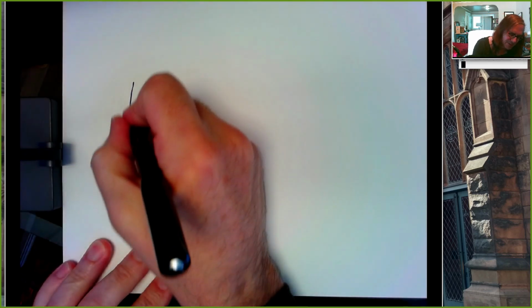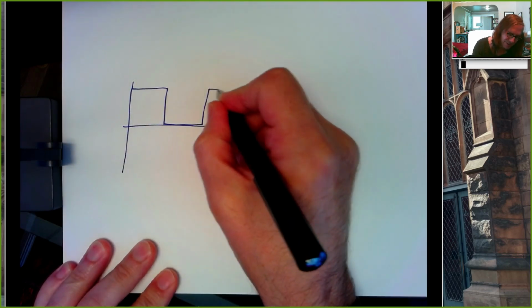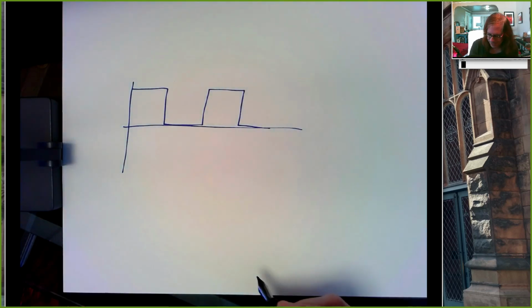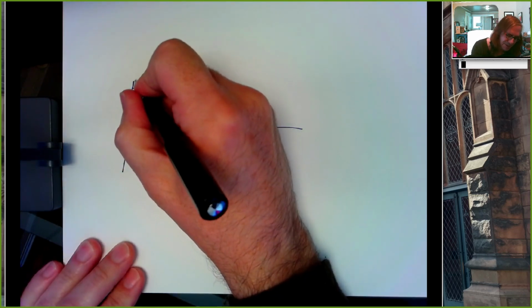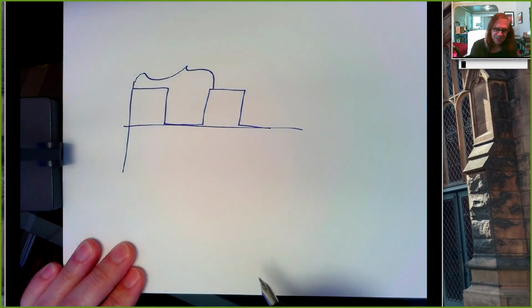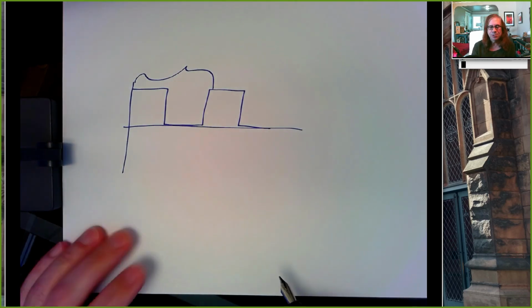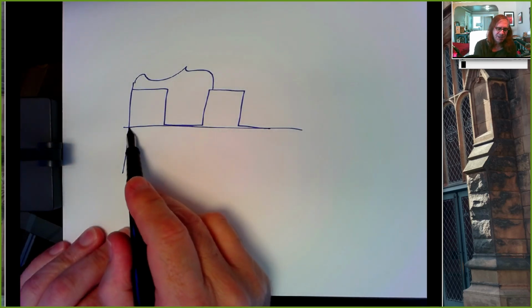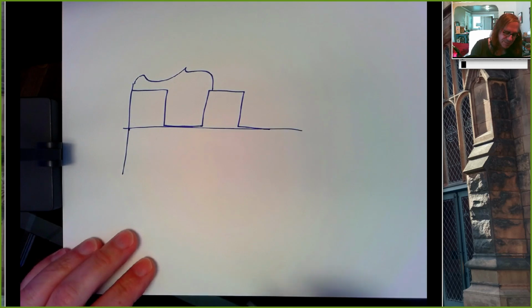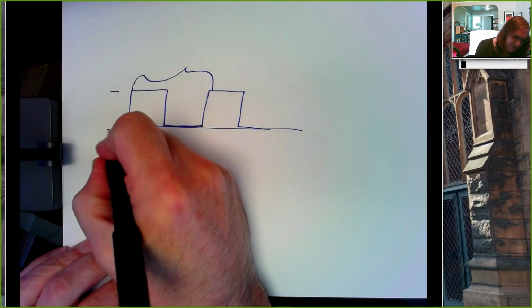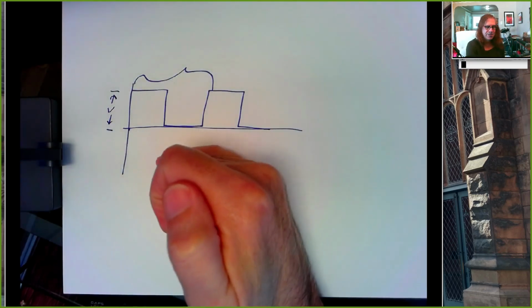The concept is, if you have a waveform, and let's just say it's a square wave like this. DC bias is how much we're moving it up and down. Frequency is how many times it oscillates per second, typically, how many times it changes from up to down in 1 second. That's related to period, which is the length of time from the beginning of one cycle to another. Amplitude is sometimes called peak to peak voltage. It's the voltage difference between the high level and the low level.